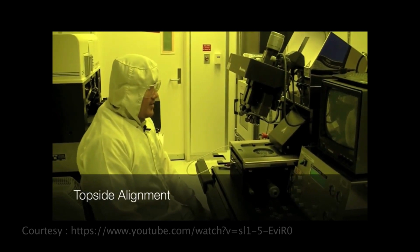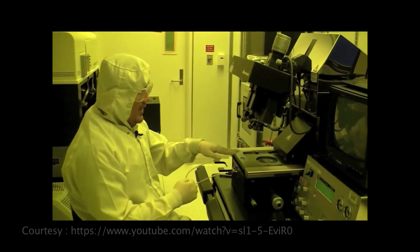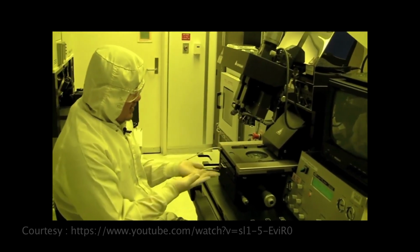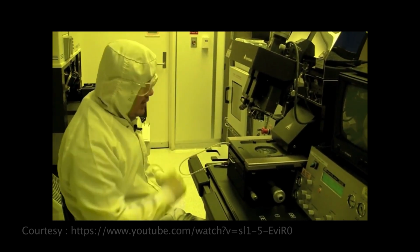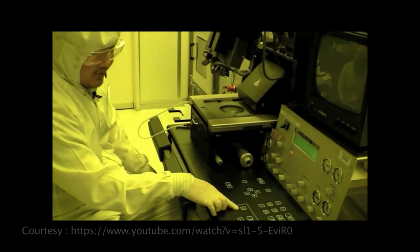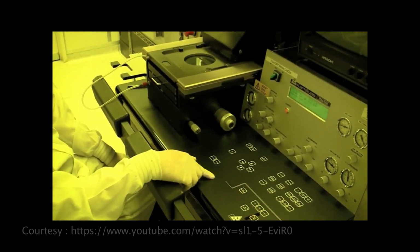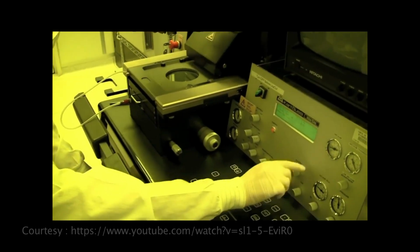What we're going to do now is topside alignment, by using the microscope on the top to align to the wafer that's underneath through the glass. So to do topside alignment, we need to move the backside microscope. So we press this button, that turns it off. Also, we need to put the illumination to the top side.